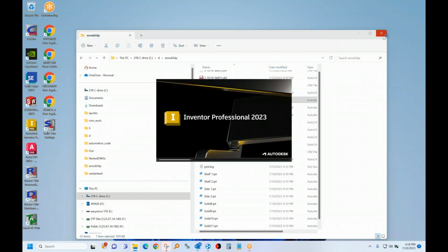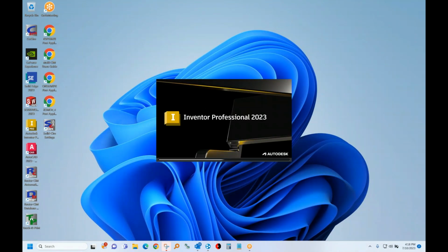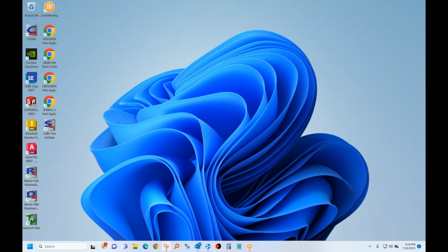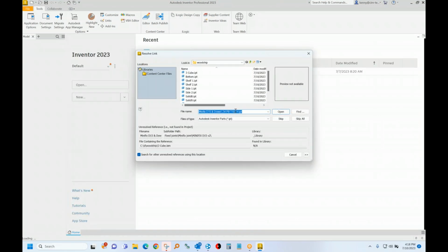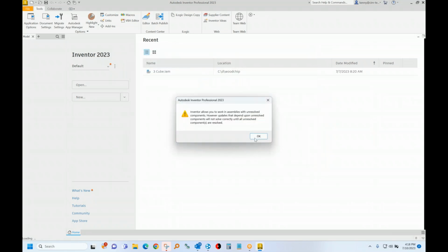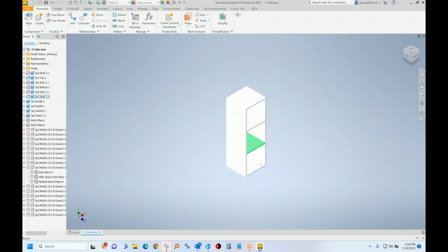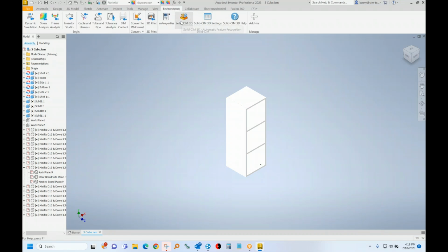I've got your assembly here. This will take a couple seconds to open up. And we'll use the material from Inventor, the part name from Inventor, and there's some pieces missing here. I usually just pick skip all there. It's no problem. It looks like it's just hardware components. And I see when you've named your parts here, you've given them part names, and you're using this as a material. You can also right-click and do part properties and put in iProperties for label fields if you like. Now, it's only one click to do the entire process.